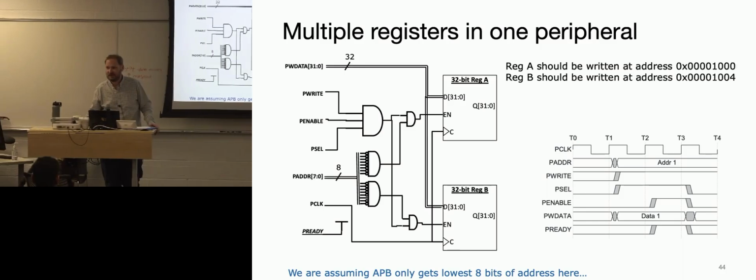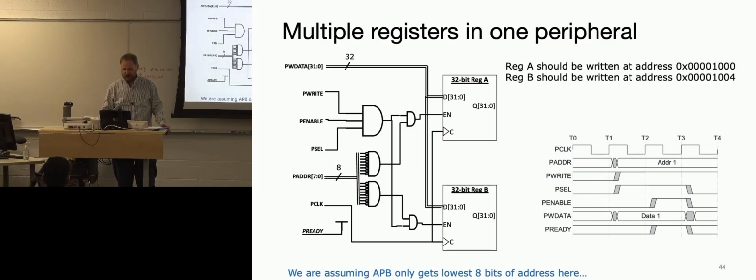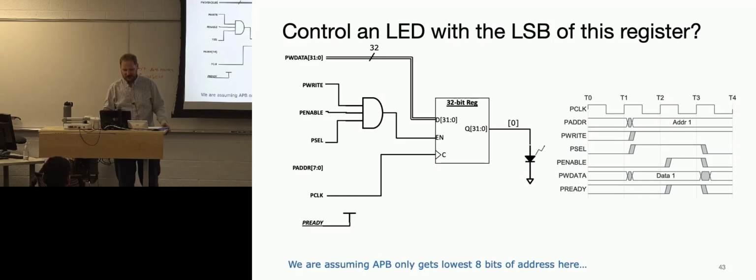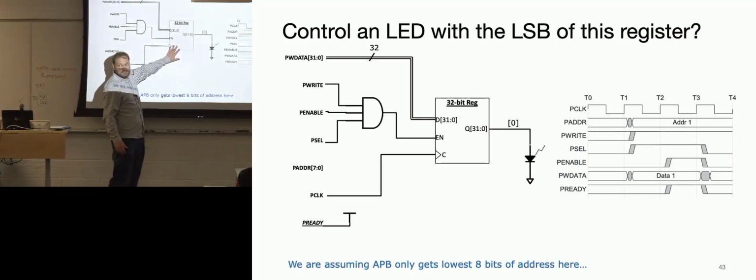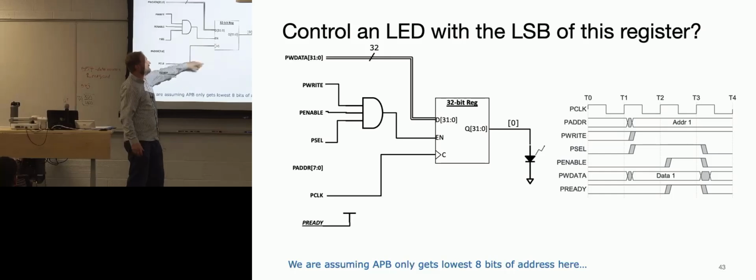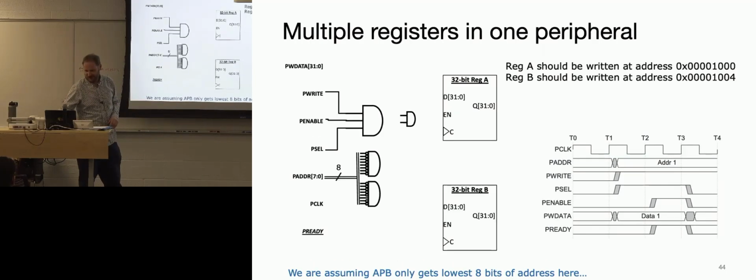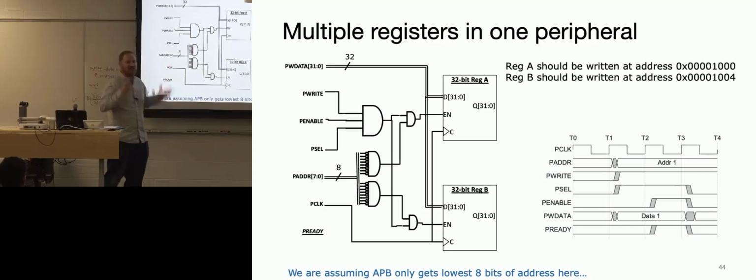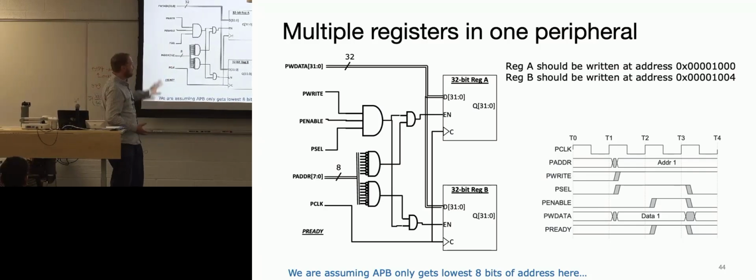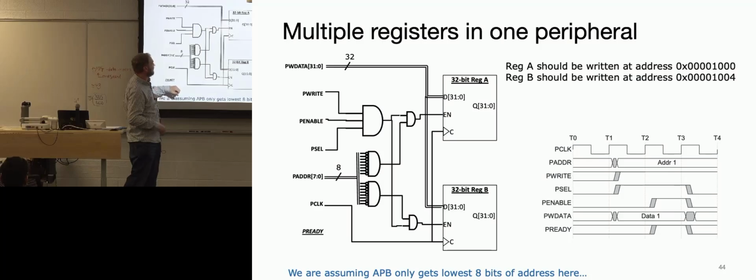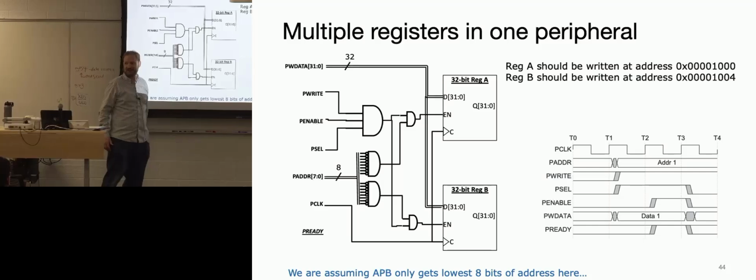Are we writing to a specific address, or just the one? No, the last one we just said the only destination here. This is the only register on that completer, or that peripheral. So P select will do the job of selecting. The most robust thing to do would have been to mask for AND. In fact, if you were at ARM and you tried to draw Professor Sample's goofy diagrams, they'd laugh at you. They'll say, no, that's not robust enough. We have a whole combinational logic suite to do the most robust thing. But this is just the minimal amount of circuitry required to accomplish that task. That's why we're showing you that.